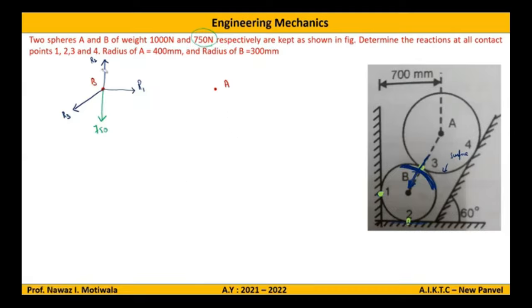Okay, so we have completed the free body diagram of B. Now let us have free body diagram of A. सबको ज्वाइन करवाना है इसका. A पे क्या क्या है? सबसे पहले अप्लाइड फोर्स कुछ दिख रहा है? नहीं है. सेल्फ वेट है, 1000 न्यूटन going vertically downwards. उसके बाद रिएक्शन फ्रॉम कॉन्टेक्ट सरफेसेस, बताओ कितने